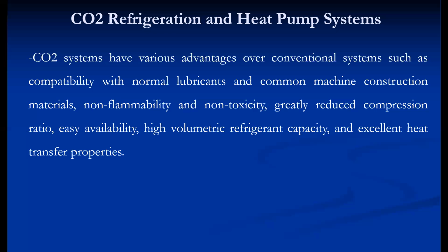If we overcome these challenges, CO2 becomes a potential substitute for R12, R22, and HFC 134A, because CO2 is compatible with the normal lubricants. It is also compatible with the normal materials used in construction piping.